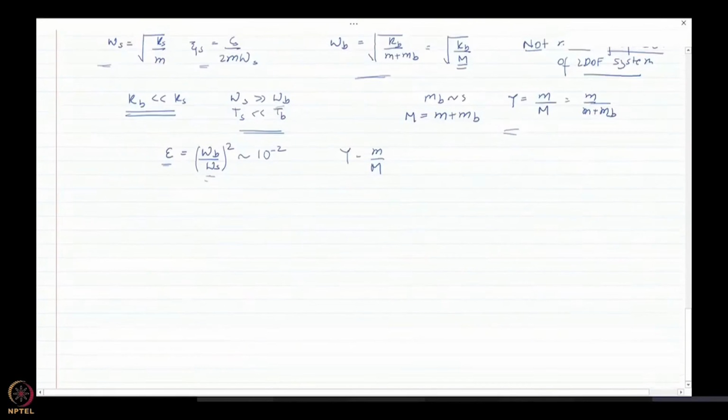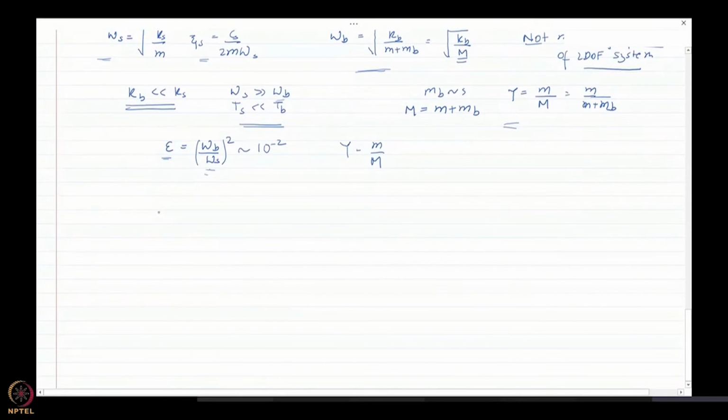Eigenvalue problem. So what do we do basically? We take the determinant of this quantity here, right? K matrix minus omega square mass matrix, and the determinant of this we set equal to 0, correct? And then we get an equation in terms of omega, and the frequencies actually provide omega square. You can think of it as eigenvalue. Whatever values of frequencies we get provide the modal frequencies. So we can do that here.